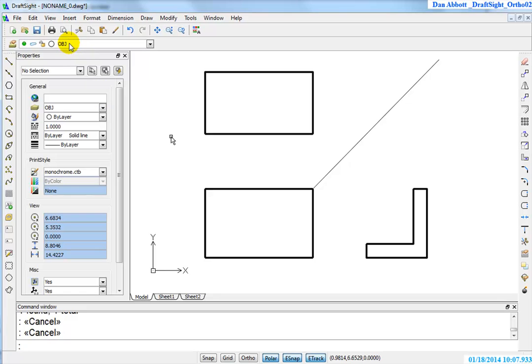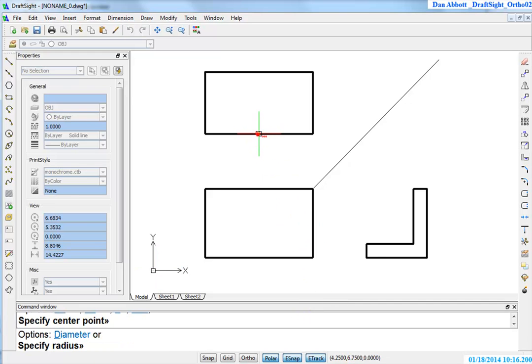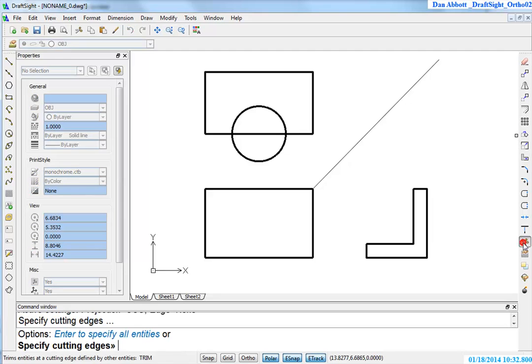Okay, I'm going to go ahead and draw a circle now. When I draw the circle, I'm going to select for the top view the midpoint of that line. When I draw the circle out, I'm going to type in a 1 for the length of the circle. And now I'm going to use a command called trim. The trim command can be found over on this toolbar that modifies things, where the scissors are, or you can type TR at the command prompt.